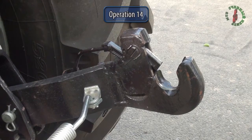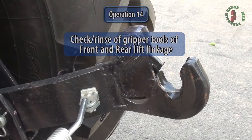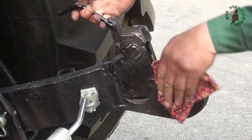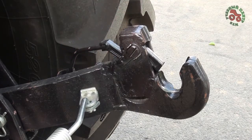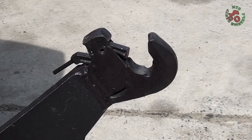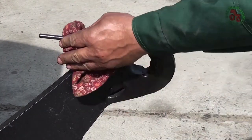Operation 14. Check rings of gripper tools of front and rear lift linkage. Check the pockets where the hinge joint locking mechanism is located in the gripper tools of the rear and front lift linkage, if installed. In case of dirt accumulation, clear the internal pockets and rinse them with water.